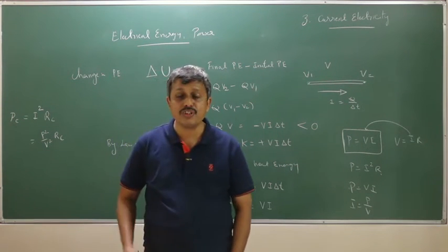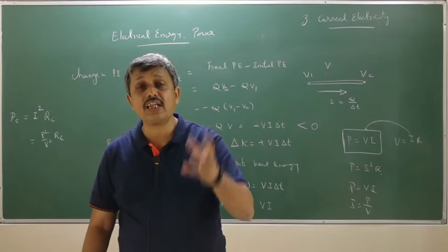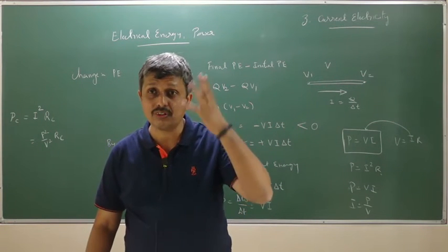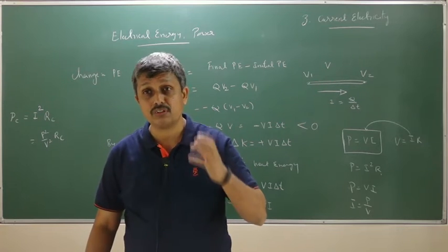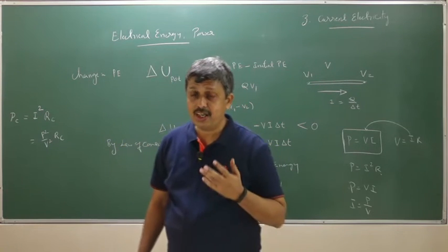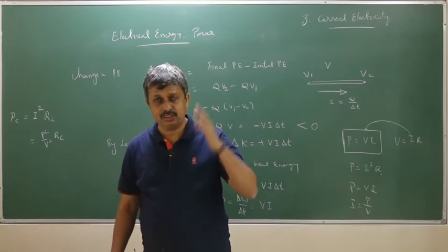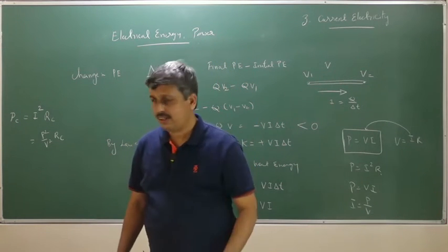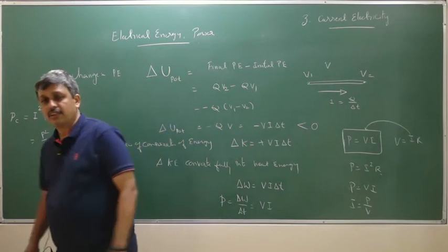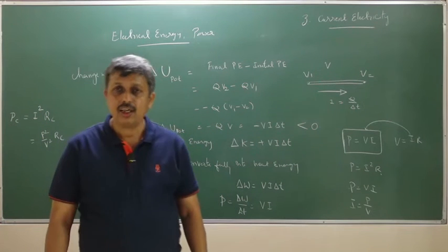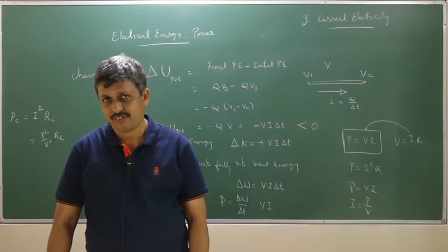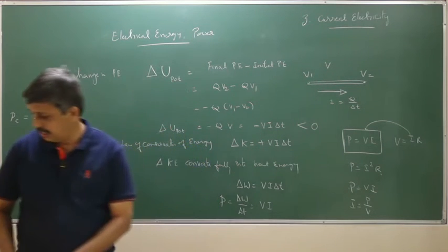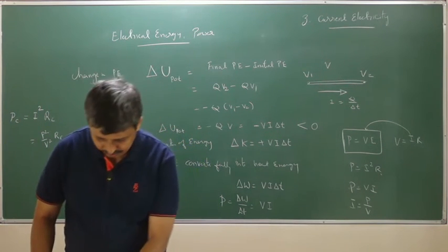That is why generally we do not send 230 volts or 440 volts like that. We send very high voltages, 11,000 volts, 6,600 volts. This is why you step up the voltage and send it when you are distributing the power, and hence reduce the power loss due to the I square R loss. So, that is basically an understanding of how this I square R loss works.